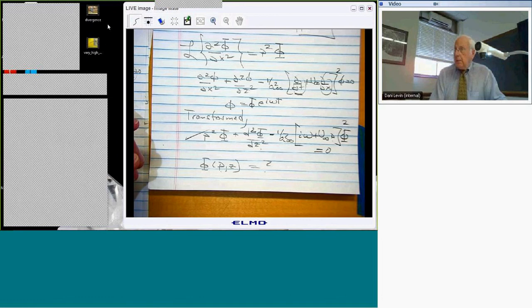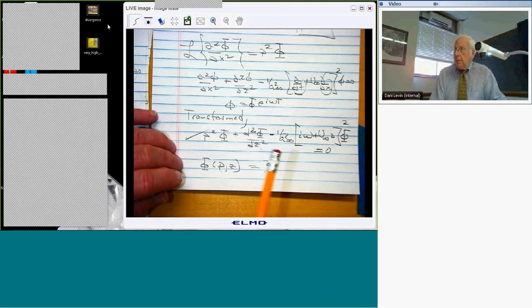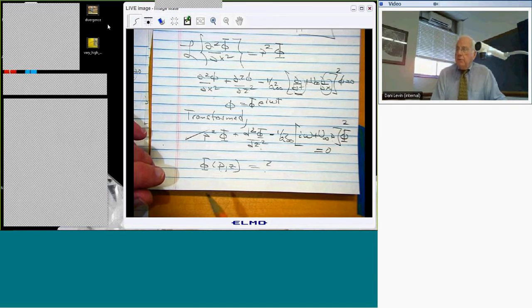The corresponding functions that appear in subsonic flow, to the extent that solutions are known analytically, are Hankel functions, which are sort of cousins to Bessel functions. So you'll get some fairly complicated functions, even in cases where you know the solution analytically. For three-dimensional flow in supersonic flow, you will need a numerical procedure to determine the solution.